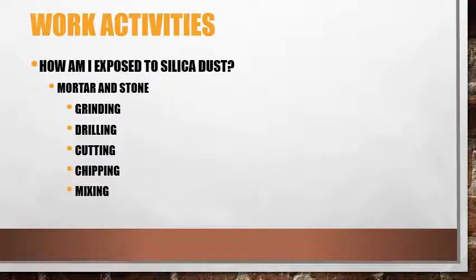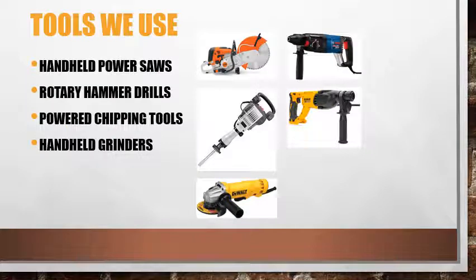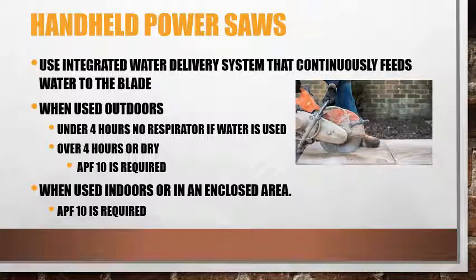Let's talk about how we're exposed to silica dust in our work activities. Anytime you're dealing with mortar, stone, brick, or block, and you grind, drill, cut, chip, or mix, silica will be present. Anytime you use any of these power tools, a hand power saw, rotary hammer drills, powered chipping tools, or handheld grinders, you will be exposed to respirable silica dust.